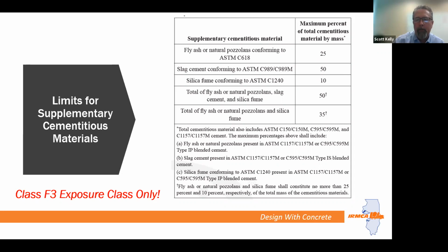And so if there's an opportunity for you to include increased levels of SCMs, blended cements, and other alternative cementitious materials, especially where 56 days or even longer ages can be considered in your construction schedule, I think that can be advantageous to providing a higher performing concrete, which will lower the global warming potential of the structure or pavement. And more than likely, as most studies show, increase the life cycle of that pavement or structure as well.